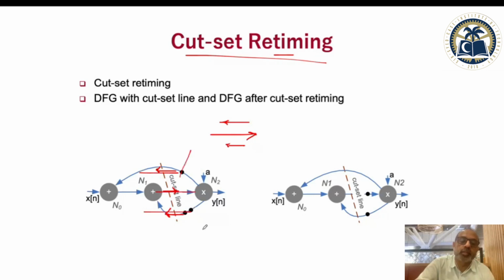So I can take this register, and this will also help you to reduce the number of registers and make them do some useful work. So these two registers you remove and bring it here. So as you can see now, there is a register here, there is a register here, and so you have broken down the combinational cloud.